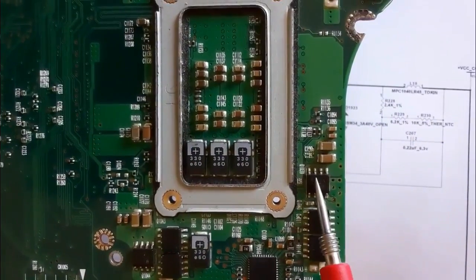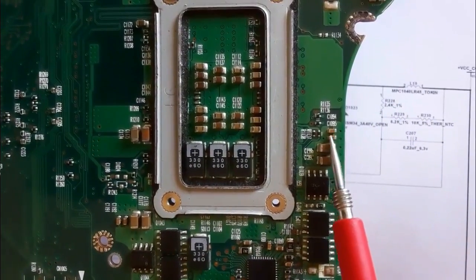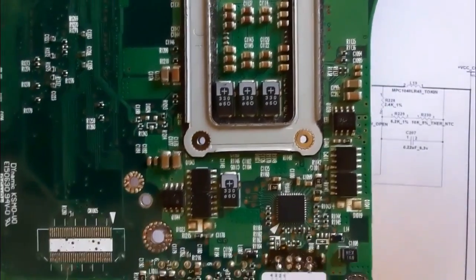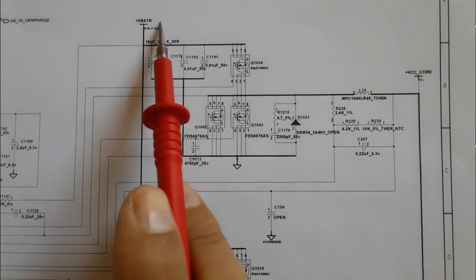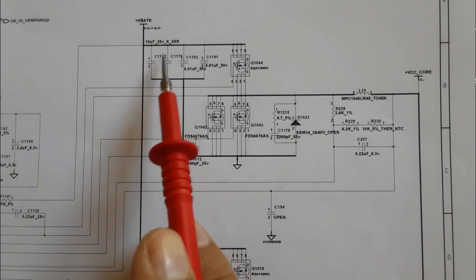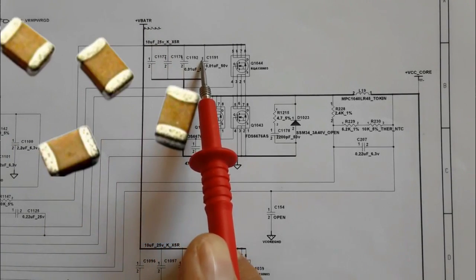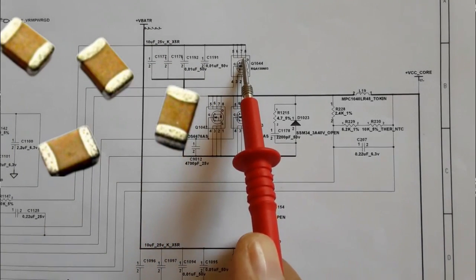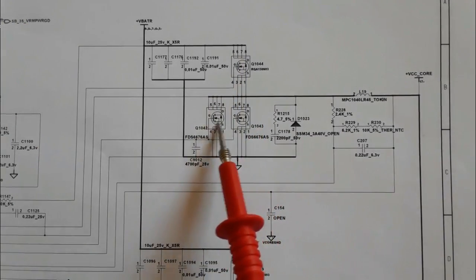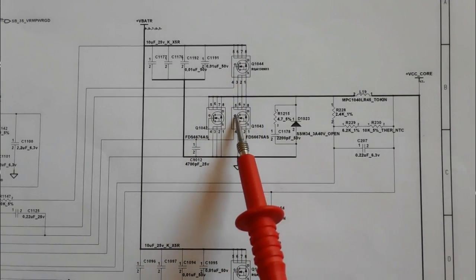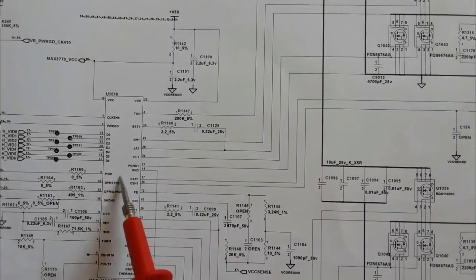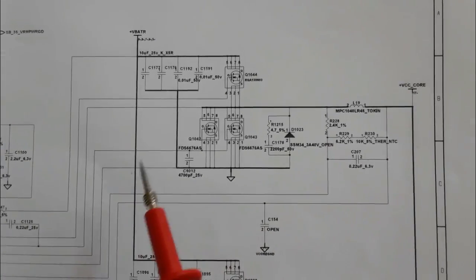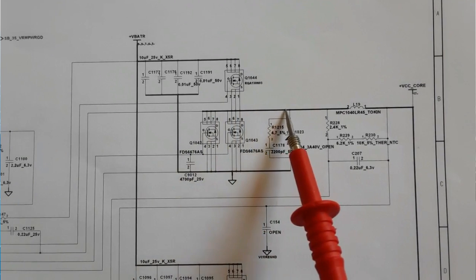The same, here we have 4 capacitors and 3 MOSFETs for the second channel, as you can see. So plus VBAT, as you can see, 4 ceramic capacitors, filtering capacitor, 3 MOSFETs. As you can see, this is the gate. This gate means the control signal should be applied to the MOSFET in its gate.